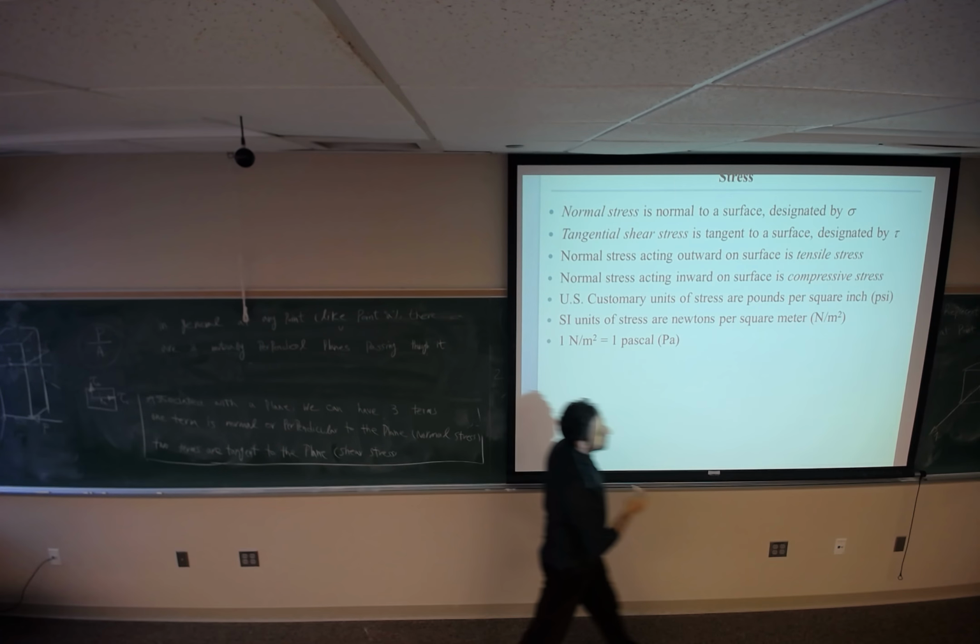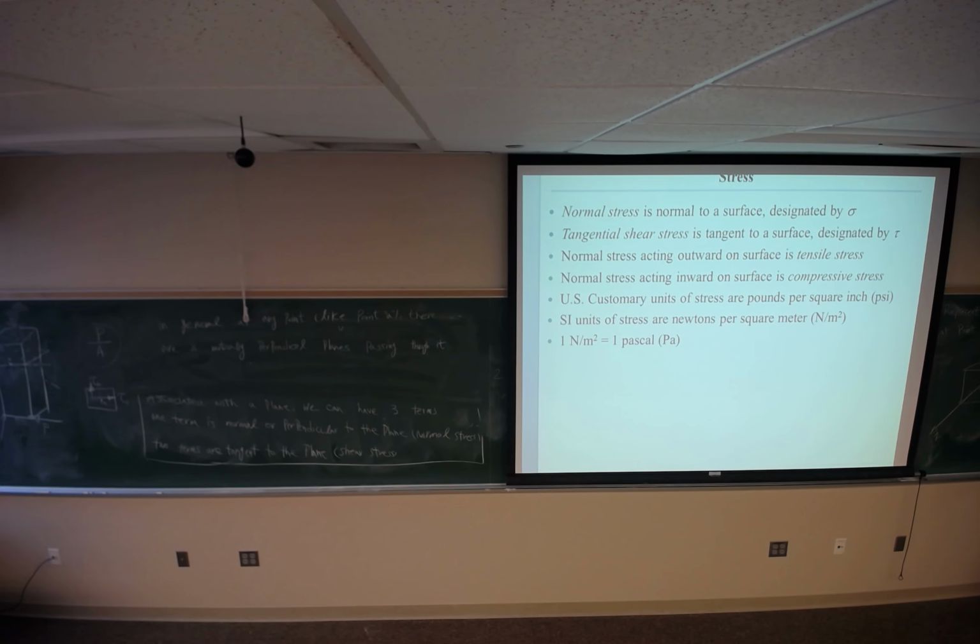I will start with this plane. This plane has the axis of x perpendicular to that plane. So I will call this plane X. If I want to show the normal stress to that, I should use the term sigma, and the subscript is going to be the axis of the plane.